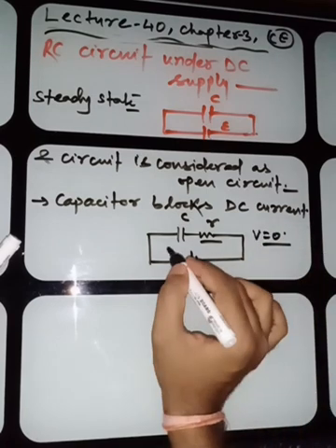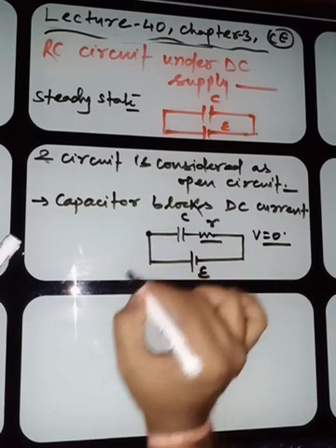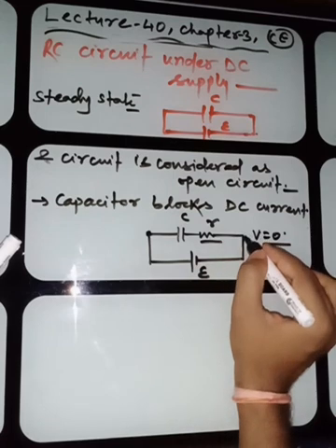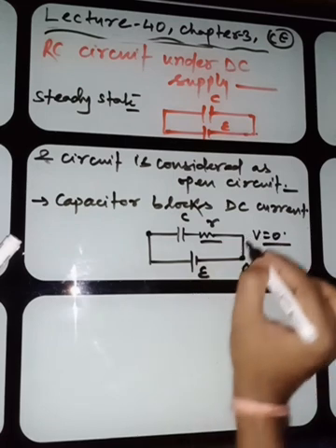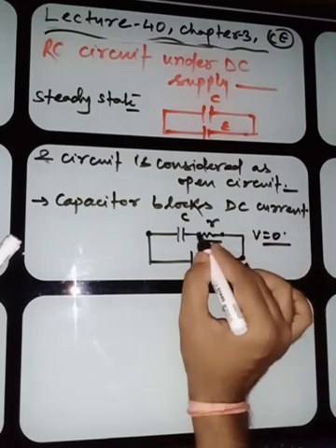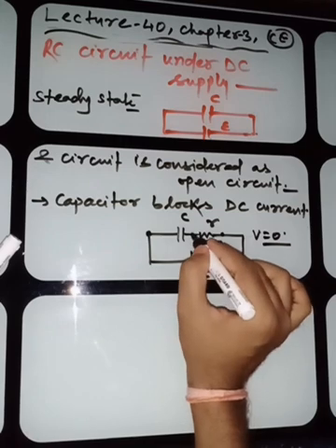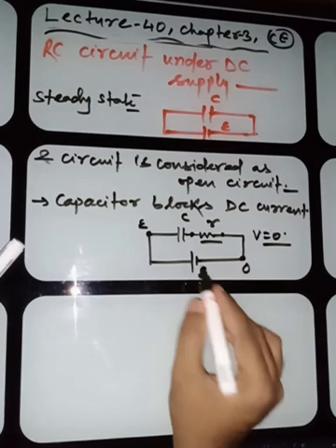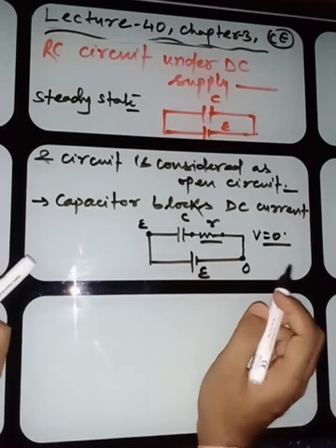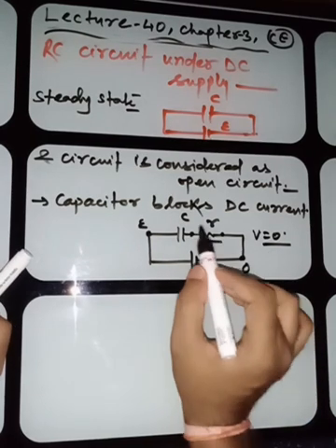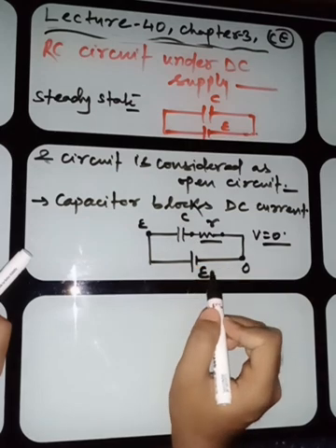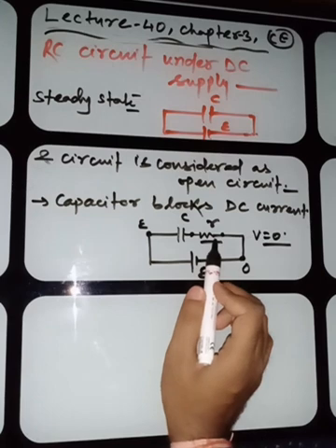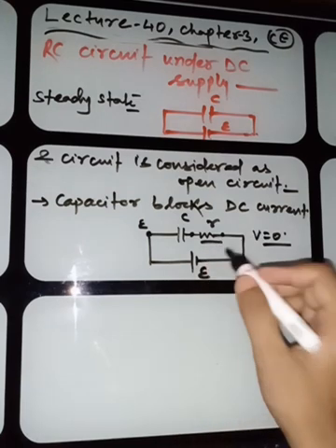It means the potential will be established over the capacitor. If at this point the potential is, suppose, 0, then there is no potential across this resistor, so here it will be 0, and here it is E. It means across the capacitor the total potential will be how much? It is E. No voltage will drop across the resistor. Remember, my dear student.